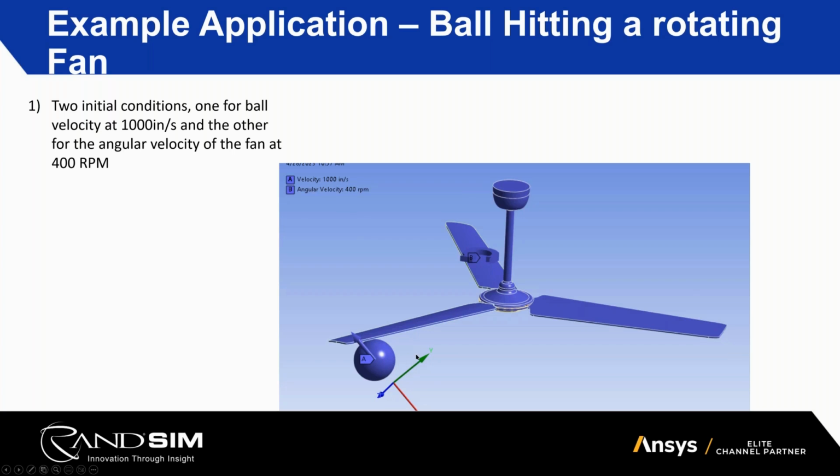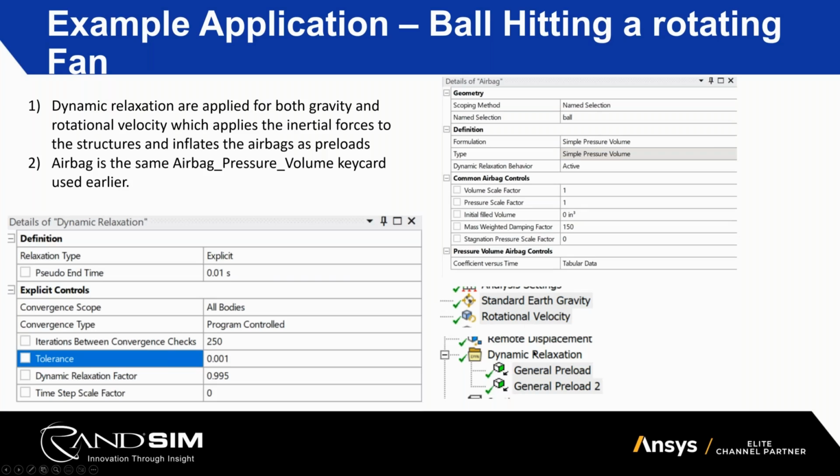Pretty simple to understand. Now, remember, when you have an initial condition, you have to do what's called a dynamic relaxation again, right? That's what I introduced earlier, if you remember. And that's basically my preload. So I preload my structure before I do the actual impact analysis. Okay, that's really what these steps are.